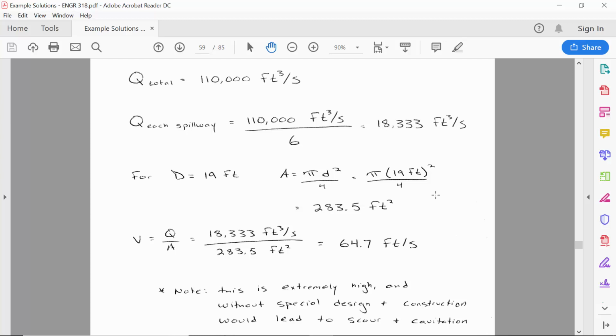For instance, a sewer pipe or a concrete curb could handle about 10 feet per second before you have the risk of damage. So beyond 10 feet per second, more careful attention has to be paid to the finish on the concrete, trying to make it as smooth as possible. More attention has to be paid to providing additional reinforcing steel in the concrete.